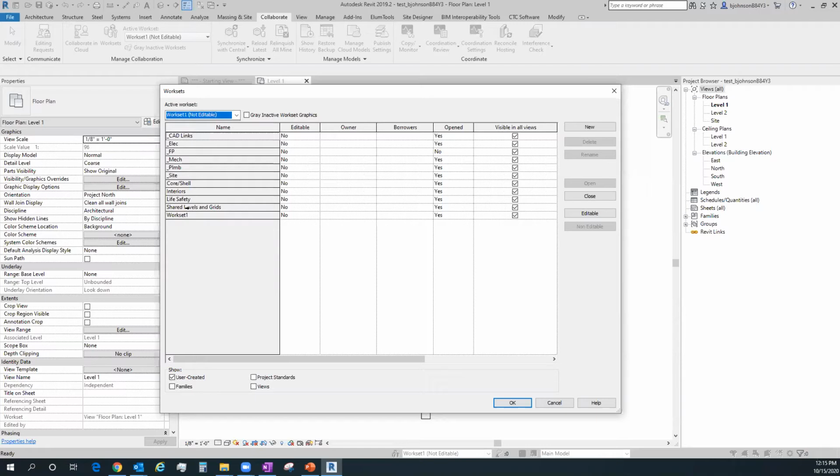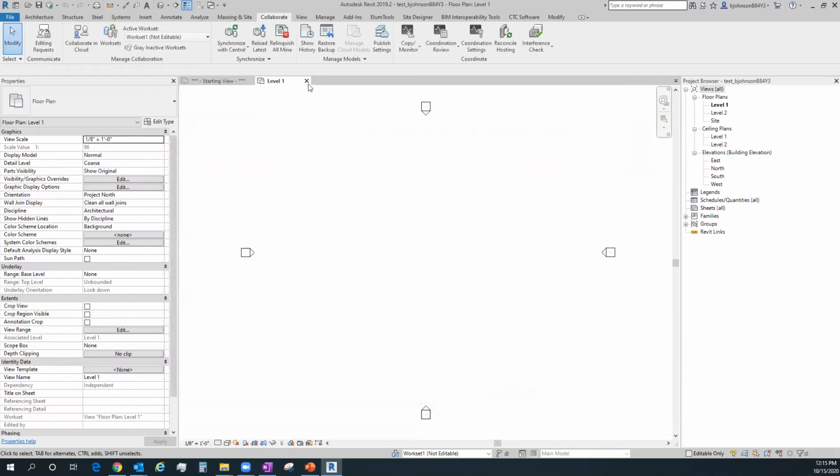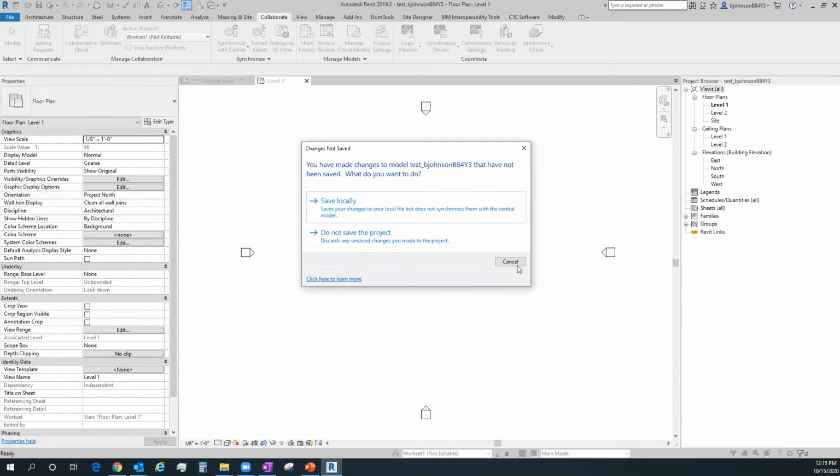If I open all work sets and it doesn't crash, it could have been that I could just have fixed it with the audit command. So that would be another way to take a peek at any basic symbol problems.